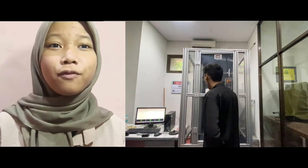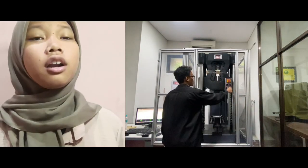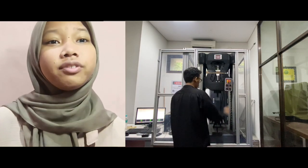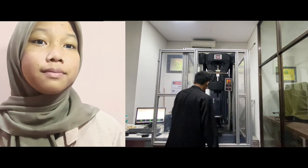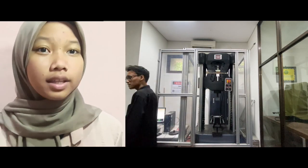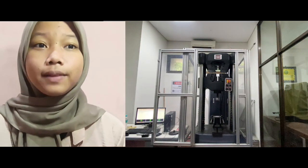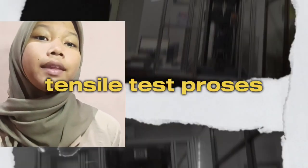Next, about the data input and settings in the UTM. Before running the test, the operator must input specimen dimensions like length, width, thickness, or diameter. Second is the test speed or strain rate according to the standard. The third is the maximum load capacity range. The fourth is these parameters ensure the machine applies load correctly and records accurate data.